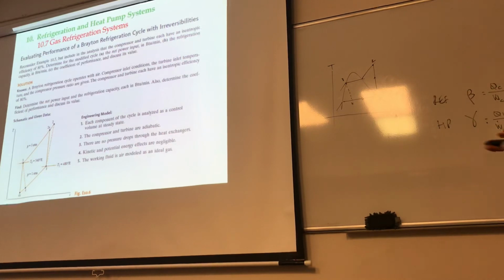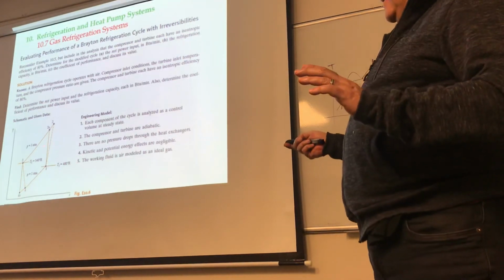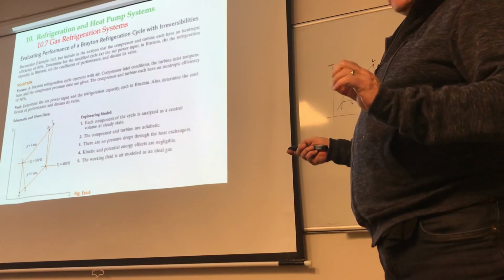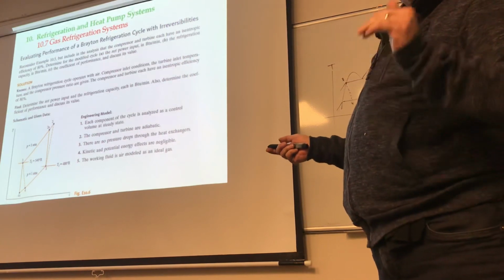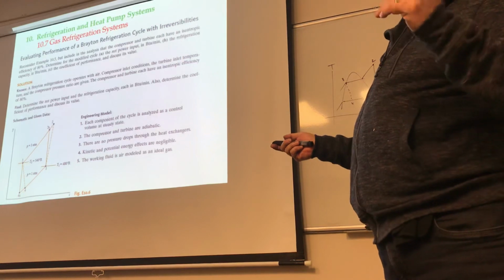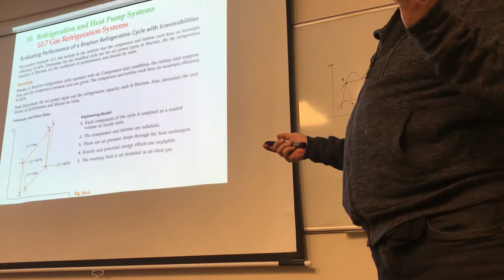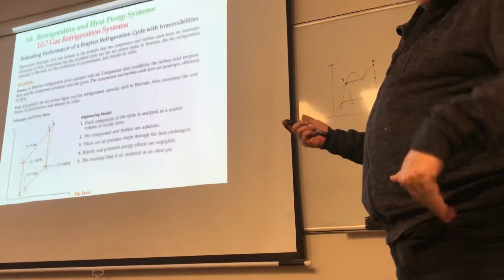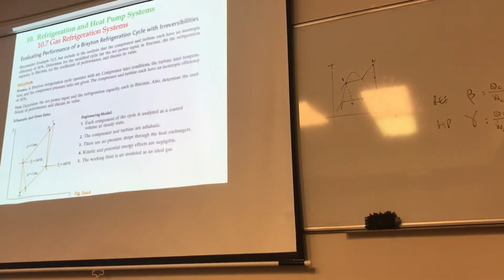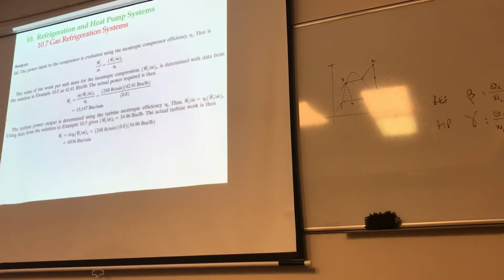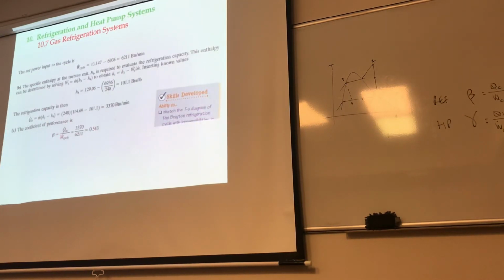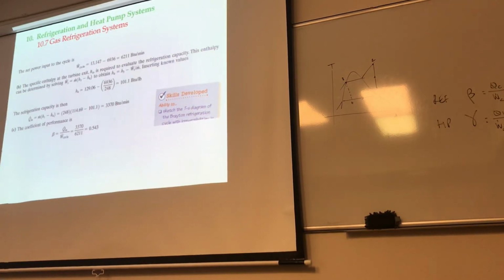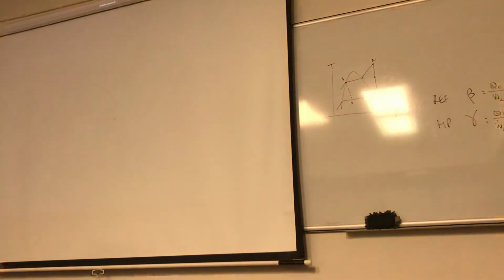That's the same problem as before, except that now you have an isentropic efficiency of the compressor and an isentropic efficiency of the turbine. What is the net effect? It's obviously on the coefficient of performance. That's going to drop down when you introduce those and you work out the numbers. You find that the coefficient of performance dropped from that 2 point something down to about 0.543 when you have inefficiencies in those things. And that concludes chapter 10.